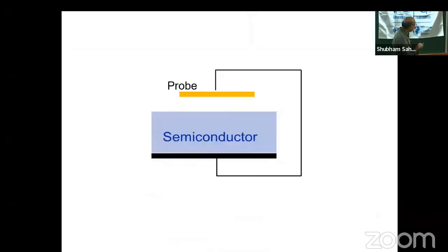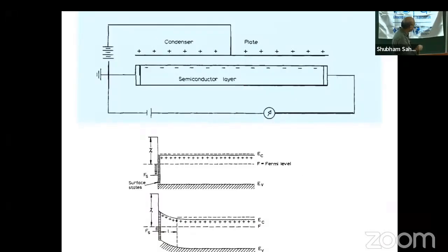So in the course of his experiments, he was looking at the effects of light, for example, trying out different materials and all that, trying to figure things out. Shockley, who had suggested using this particular structure to create an alternative to the triode, said, well, why don't we go to lower temperatures? If we go to lower temperatures, then the surface states will not respond, and maybe if we alter the voltage here, we will start seeing changes in the bulk. So he suggested doing experiments at lower temperature to immobilize the charges at the surface.